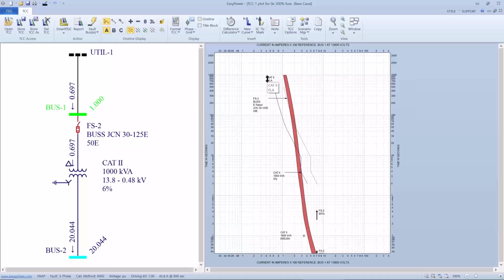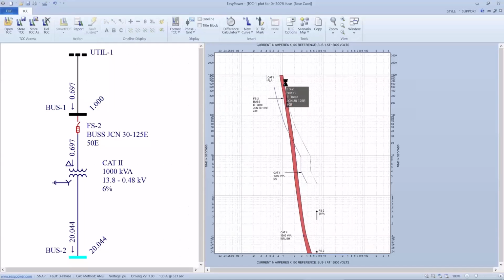So 300% times that would be 120. If I look again at my coordinates, if I have a fuse at this point, it's giving me 130 amps protection, which is just on the hairy edge of the 120. The NEC says I can pick the next value up if I don't have the value of 120. If I look, the 40E gives me 114. So to be a little on the safe side, I'd pick that lower value.